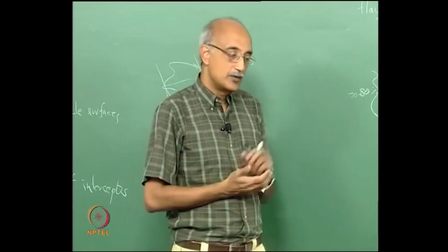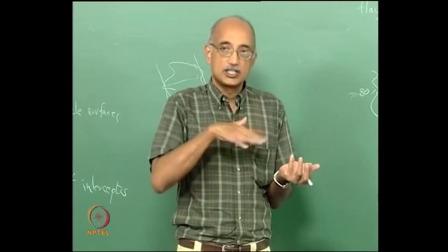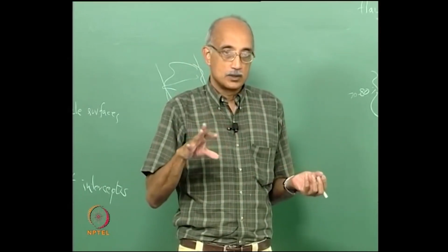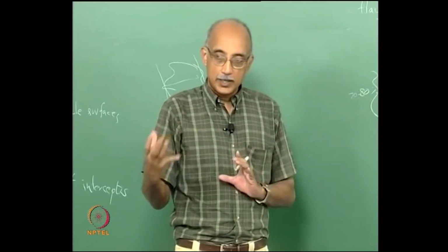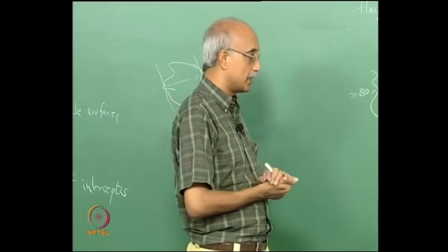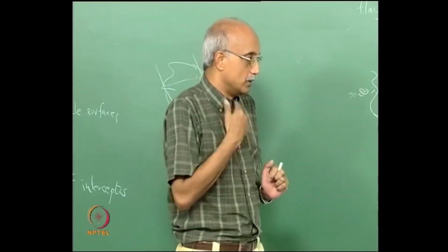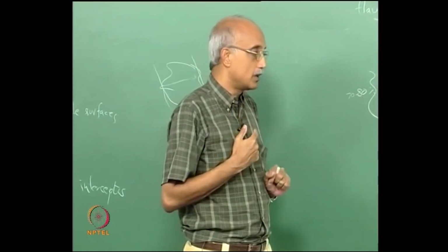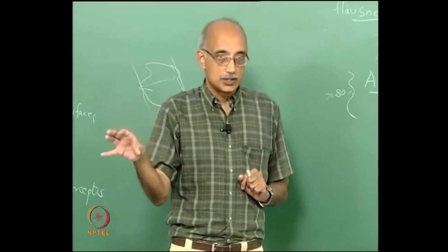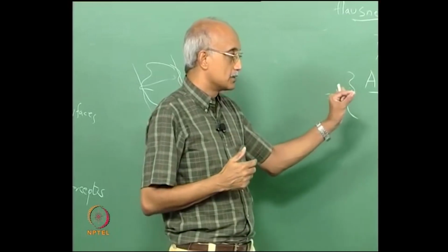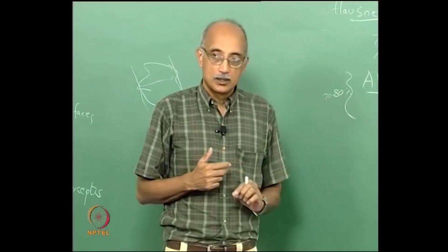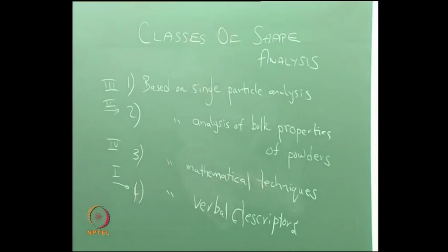Every shape will have a distinct spectrum, so if you have a sufficiently good library of reference spectra to compare to, you can simply compare the Fourier spectra for the shape of your particle versus the library and draw a conclusion. So there are several subcategories under the mathematical techniques class of shape analysis methods.